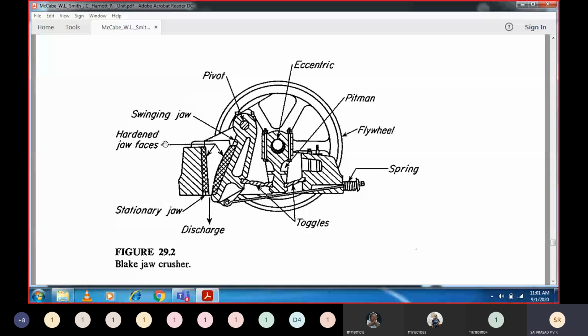So if you put a 20 centimeter particle, that will not be falling into the system. Only 10 centimeter will go. So remember always, if you have a feed of uniform sizes, it is always good for us for increasing the efficiency. If we have a feed of very different sizes, for example, the opening between these two is 10 centimeters, and you are putting a 1 millimeter particle, what will happen? It will easily pass through it. Energy is given to the machine, crushing is not taking place.